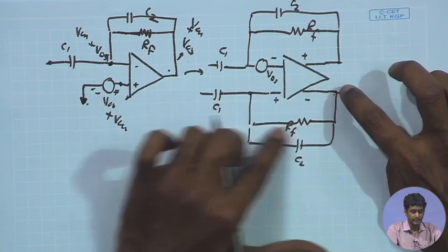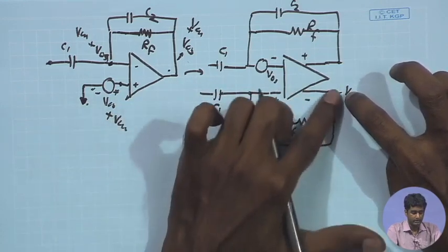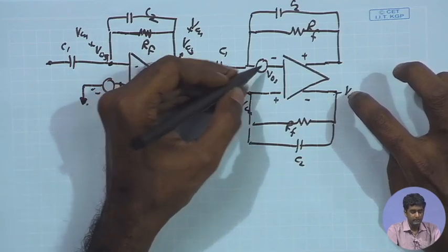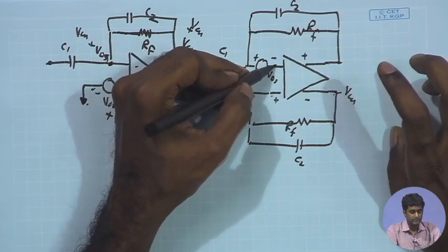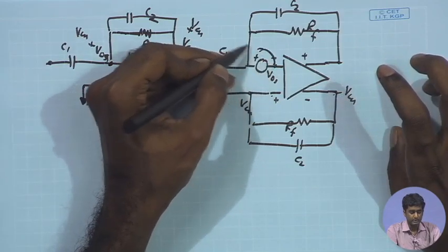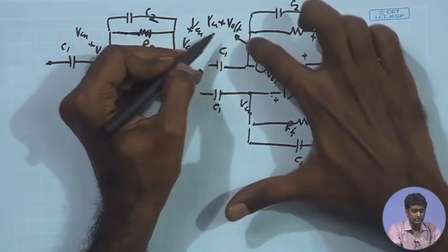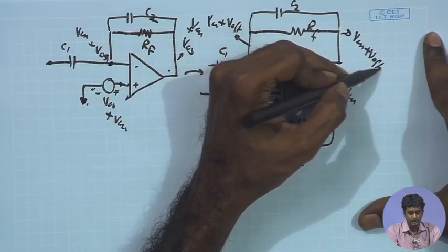Once again, because of this resistive feedback, you do not have any AC or DC current flow through this capacitor. This has to be once again VCM. However, if I take the polarity of the V offset in this fashion, this again has to be VCM, and this therefore becomes VCM plus V offset, and as a result this particular terminal has to be VCM plus V offset.